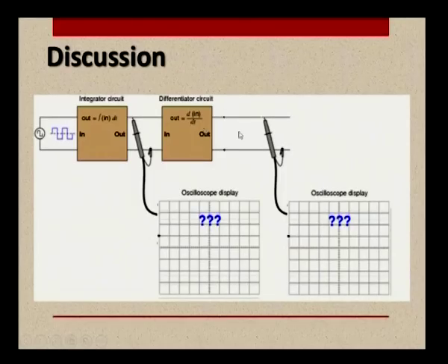But as far as the waveforms are concerned, one thing we can immediately guess: the integration operation is nullified by the differentiation operation. So, here also with this basic knowledge about the integrator and differentiator, we can quickly make a guess for the output of the typical combinational circuit. Let us have a look at the slide.